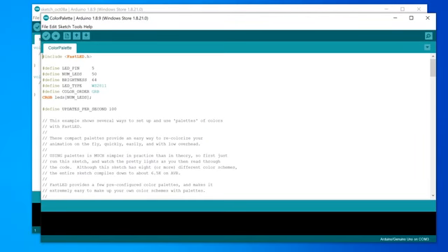You will need three main parameters: LED pin, number of LEDs, and brightness. The LED pin defines the data pin from which we will get the data signal for the LEDs. The NUM_LEDS defines the number of LEDs. Here I will connect two sets of LEDs, 50 each, so it means that the total will be 100 LEDs. So I will change the number to 100. Now the brightness.